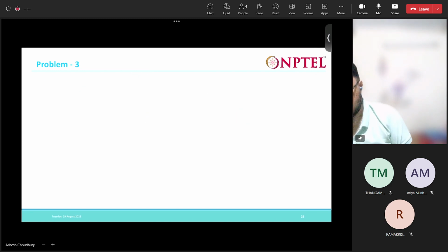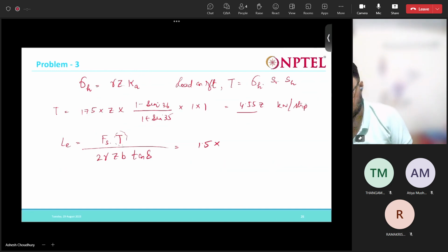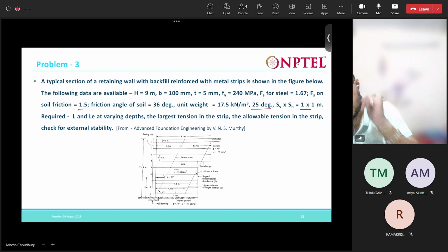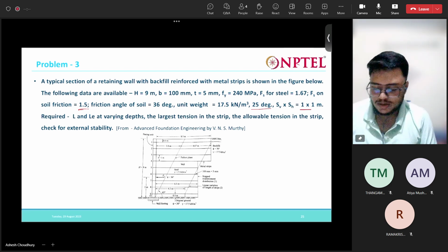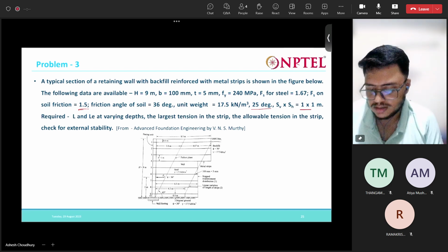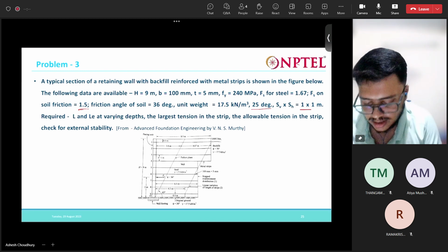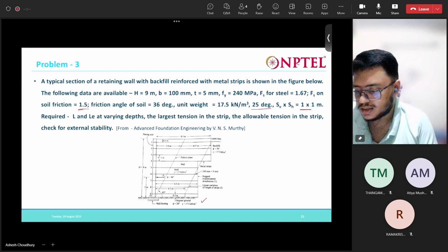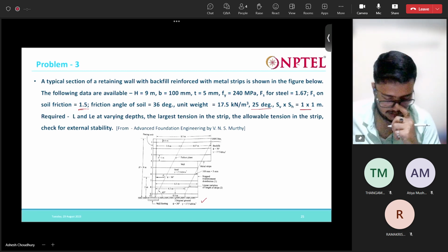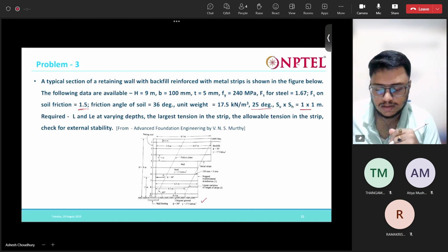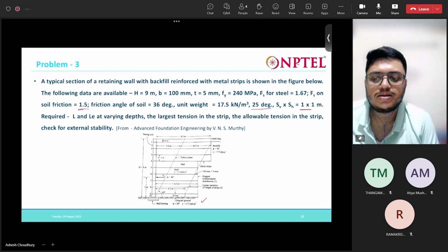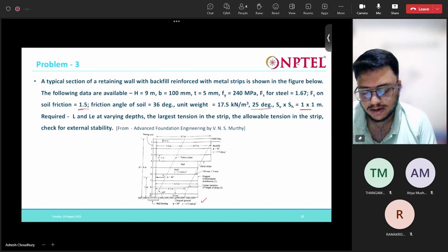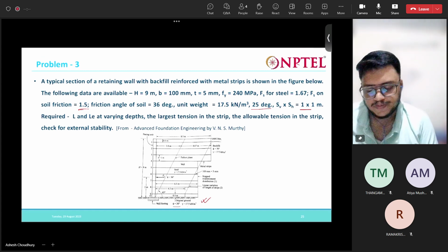All right, so the sliding factor of safety we checked, and the overturning factor of safety is checked. Next, you can find out the bearing capacity, the factor of safety in bearing, by yourself. For the original count, phi and gamma are given.